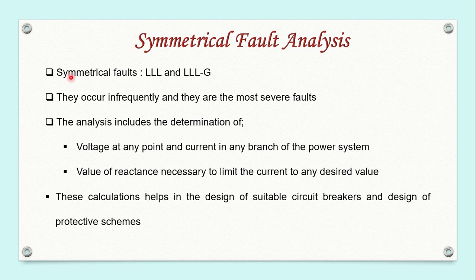And we know that the various symmetrical faults or three-phase faults are triple line, and triple line to ground: short circuit between all the three lines, and short circuit between all the three lines and the ground. We know that they are the most severe faults, and their frequency of occurrence is very low. They are the least frequently occurring faults and the most severe faults in the power system network.